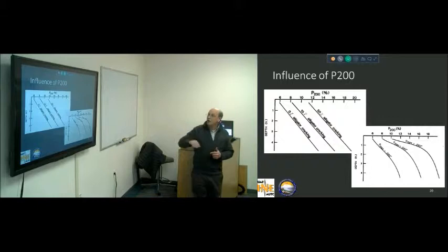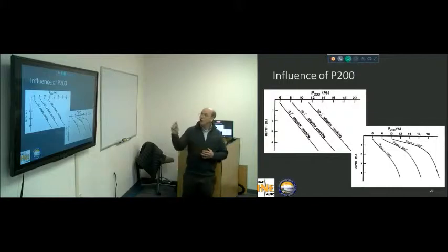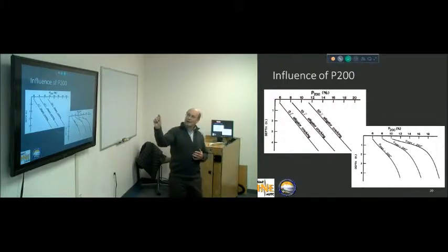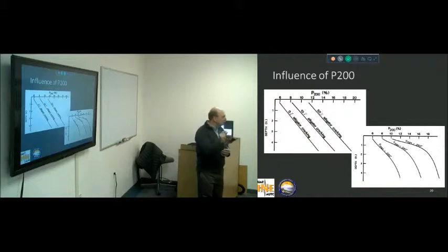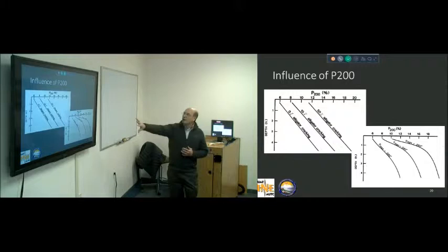Really good thing. We applied the same thing with our deflection, and we found that as you increased it, it's interesting to note, 2% fines can make a huge difference. 2%. And yet sometimes we don't pay enough attention to that, at least in this methodology.